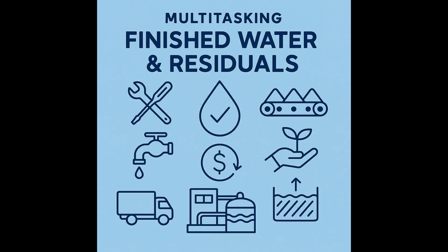By forming larger flocs, the polymer makes it much easier for the mechanical equipment, the centrifuge, screw press, or BFP, to separate the water from the solids. Without effective polymer conditioning, the sludge would stay watery, and dewatering would be inefficient or maybe wouldn't work at all. Okay, so they're critical. Are there different kinds?